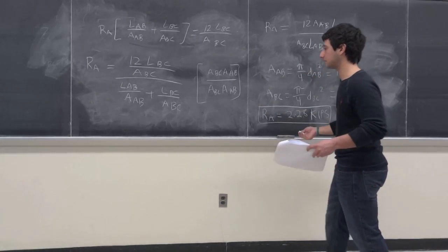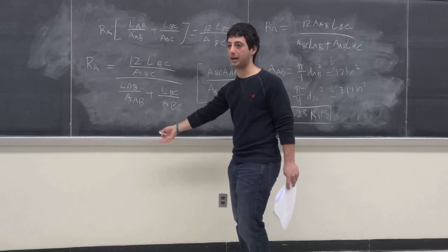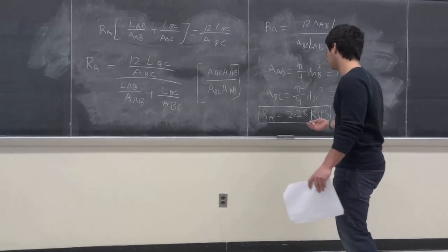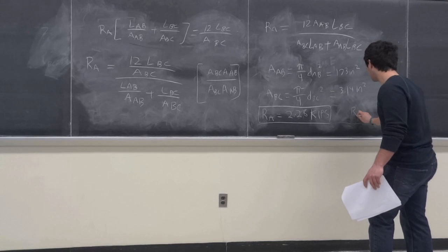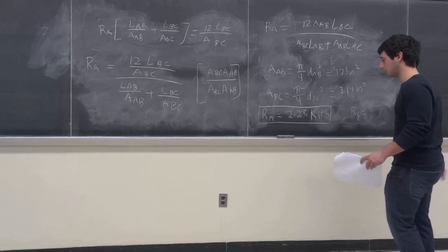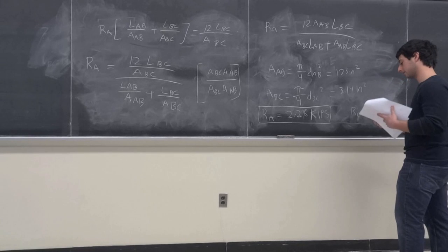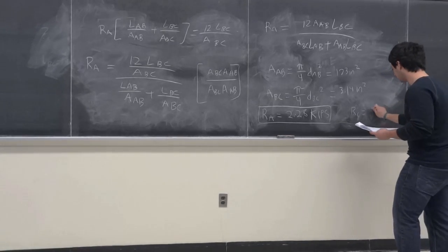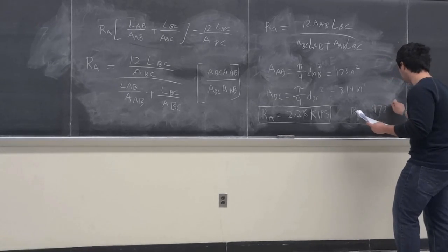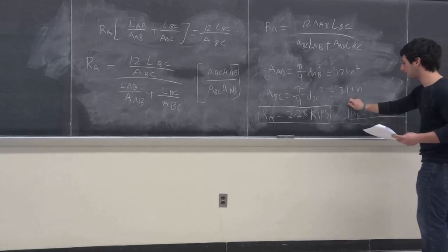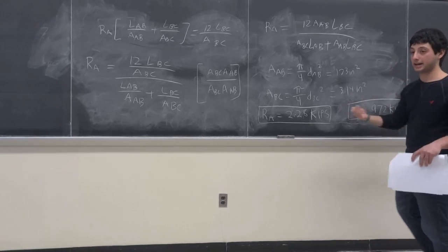All right, so that's one reaction. And then the other reaction, you could go back to the statics. You had R_A plus R_C is equal to 12, right? So then you could get R_C is equal to 12 minus 2.28, and you get 9.72 kips.